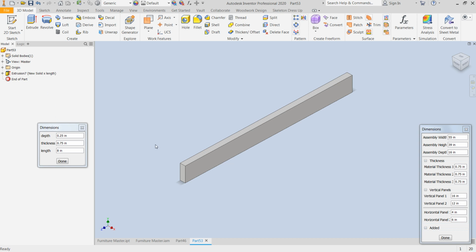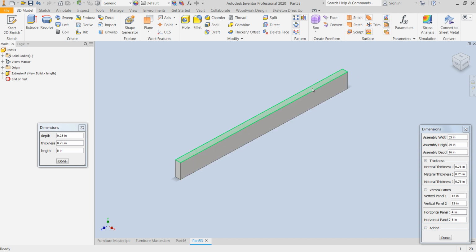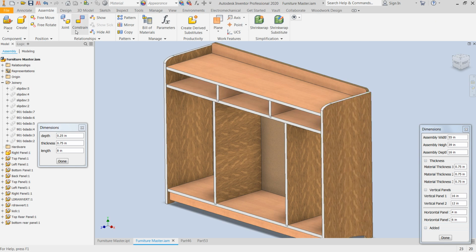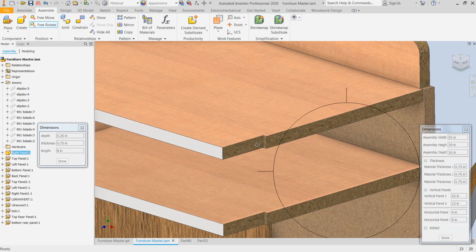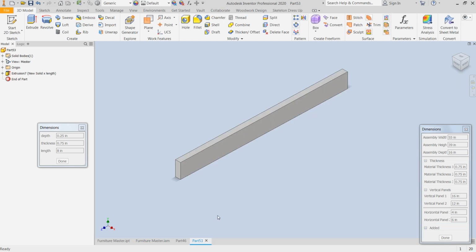Now, one thing is, this is going to be what I consider the actual tenon. Really not a tenon, but if we rotate it, what you're seeing here is going to be this piece to where it stops. Because if I change the length, then I can have a blind dado. If I say it's the full length, then it's not a blind dado anymore. And if I define steps or whatever, that's what they are. So what your joint looks like really determines what I'm about to do.